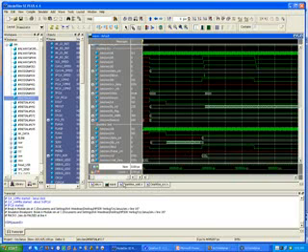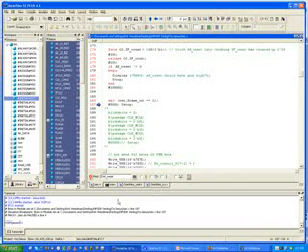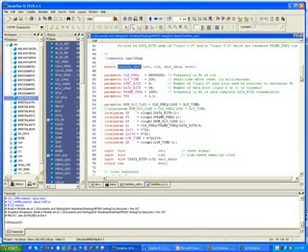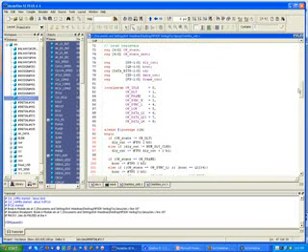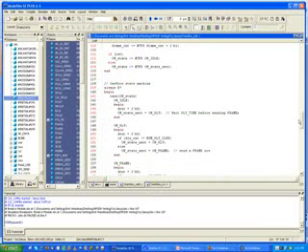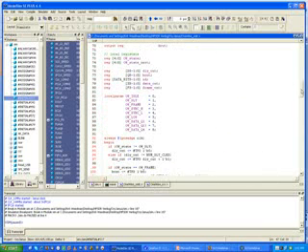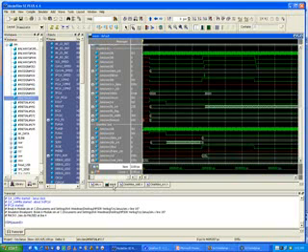And then what happens? Well, if we go back to our code here, the transmitter, remember I have this value num delay clocks that calculates a certain number of clocks based on the frequency and everything. In my state machine for the transmitter, basically in this state, this OW delay, it waits for that before it advances to the next state, which is OW frame. So let's look at OW delay. That's a state value of 1, and frame is a state value of 2.